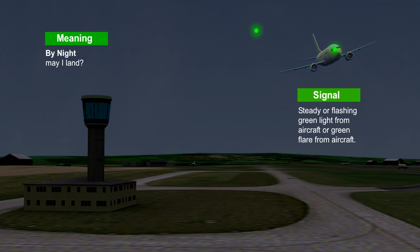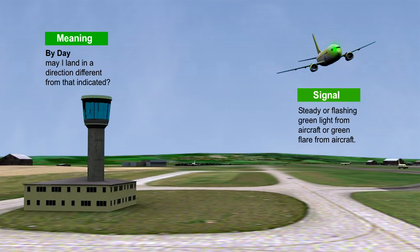A steady or flashing green light or green flare from an aircraft means that the aircraft is asking to land if at night, or, if by day, asking to land in a different direction from that indicated.